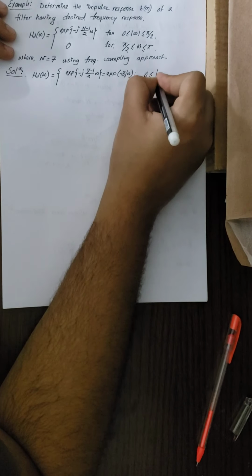Now for the third and final step, what we need to do is determine the impulse response for the real coefficients. h of n equals 1 over N times H of 0 plus twice the sum over k from 1 to P of the real part of H of k e to the power j twice pi k n over capital N, and P will be equal to (N minus 1) by 2 for odd and equal to N by 2 minus 1 for even.